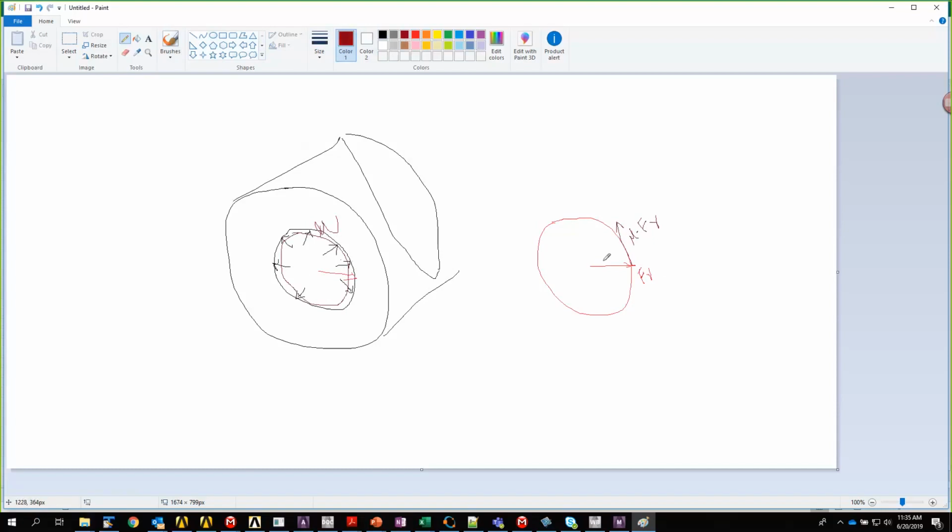Okay, this is the tangential force. This tangential force will be acting at every point in that interference radius. This is the radial force. This whole thing is a tangential force. This tangential force times this radius is the torque this joint can take.